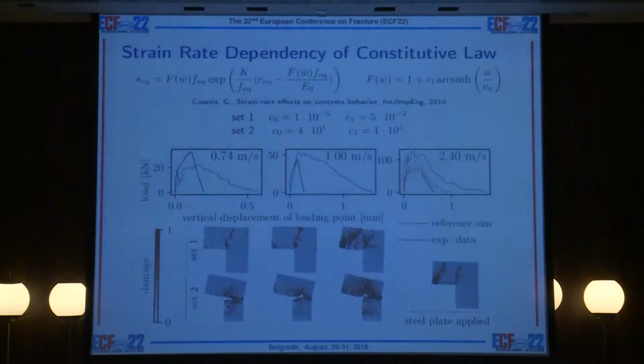But the problem was that the force sensor was as close as possible to the specimen in the experiment, but still there was some small steel mass between the sensor and the specimen itself that affected the response. So if we modeled this directly, we could obtain a much higher loading force that is comparable to the experimental evidence.